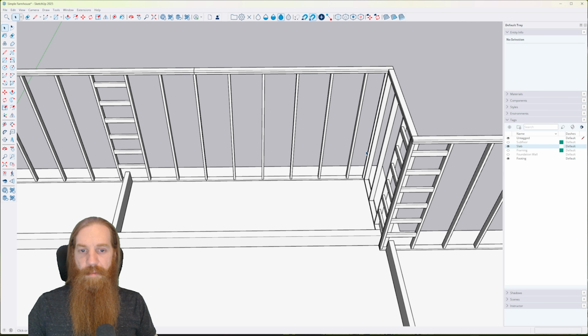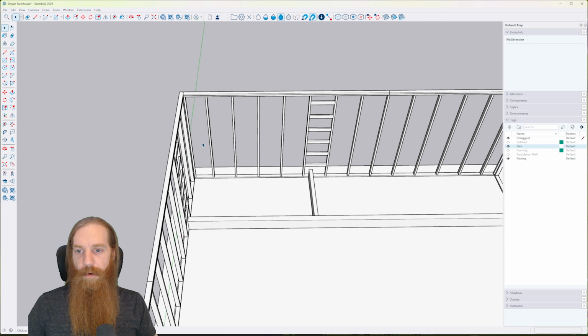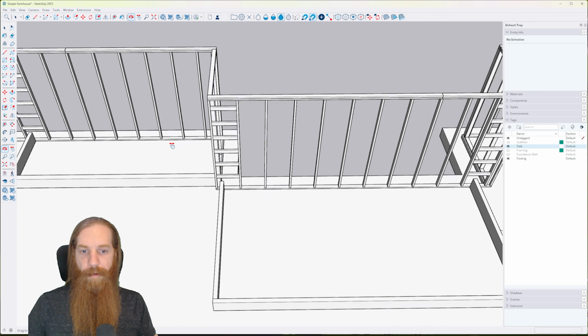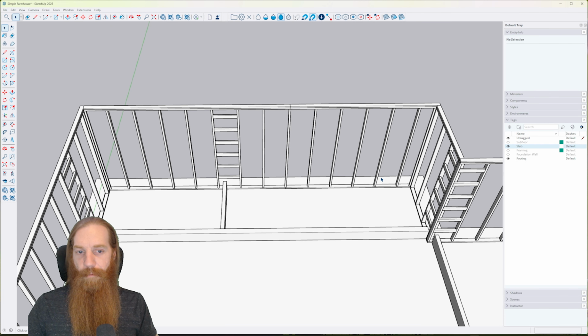So we're left with something smaller down here, but that's okay. I just want to make sure I'm always starting from the same end on every wall that I do. And that way it will be exactly the same as what I would do when framing these walls in the field at the job site, because I would always start from the left end and work my way right.